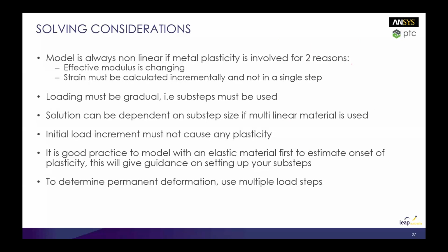You don't want to put a load and then have it go straight into plasticity, because it will struggle to converge. If you've got a multilinear curve, the solution you get will be dependent on the substep size, because you're jumping from one point to another. And if you do a large jump, then your strain history will not be captured accurately.